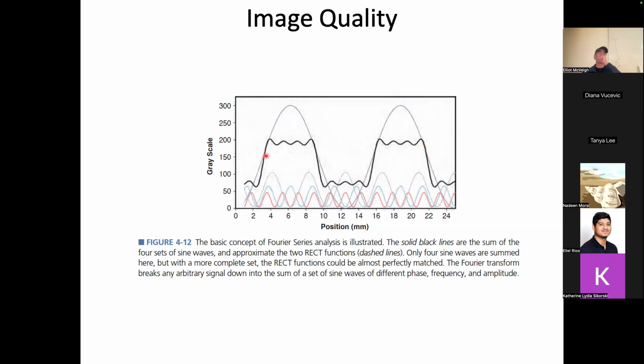It's an interesting thing when you look at discrete Fourier composition of functions, you're still going to get a little ringing on these edges. Even as you go to higher and higher frequencies, the ringing will be pretty well the highest frequency you include, and it'll be right at the edge. It'll go zing, zing, zing, zing, zing, ring down, right? So it's hard to make it a perfect square. What happens at these edges here is you get a little ring down.